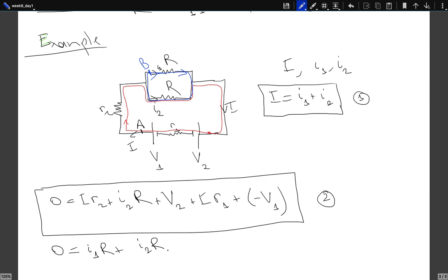So this is a higher potential point than this one. So here, as I go from this point to this point, there is an actual potential increase, not a decrease. But an increase, again, we just write as a negative decrease. And this is my third equation.